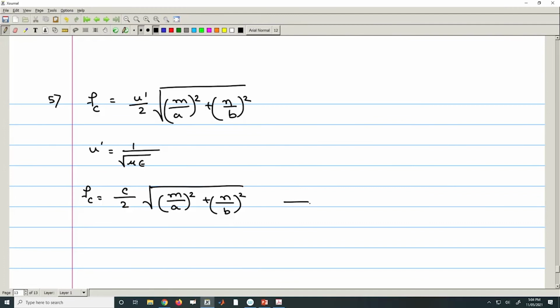So, it is said that we need to calculate the dimensions of an air-filled waveguide for which the cutoff frequency for TM11 and TE03 modes are equal. Now we will calculate for TE11. So it comes out as, substituting the values, m is 1, n is also 1. So 1 upon a squared plus 1 upon b squared.